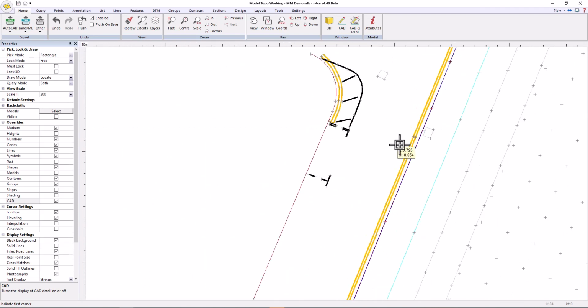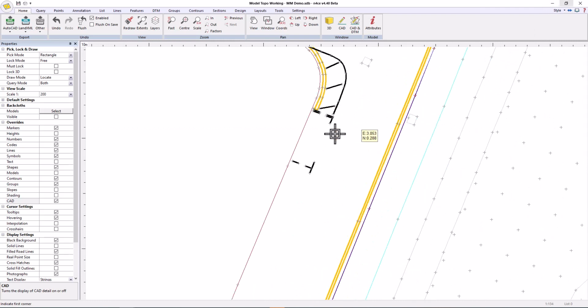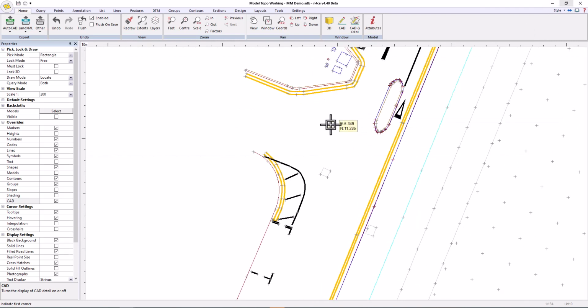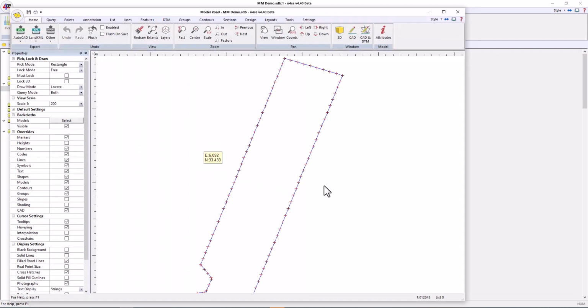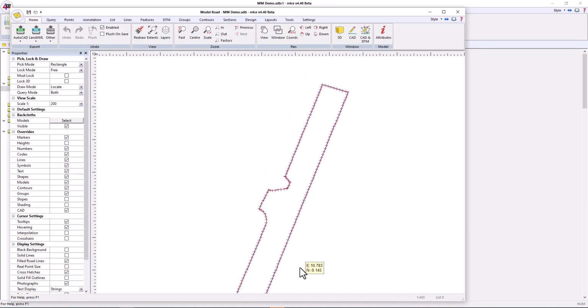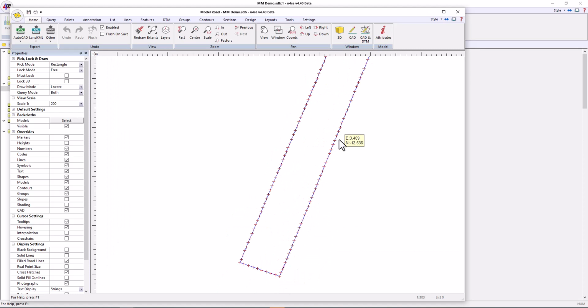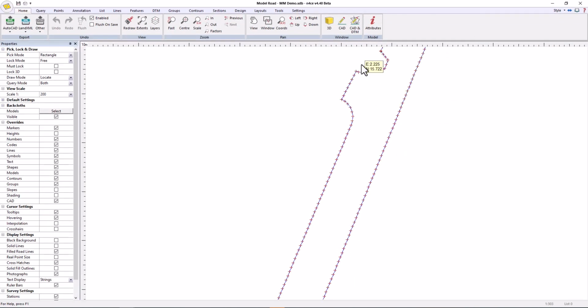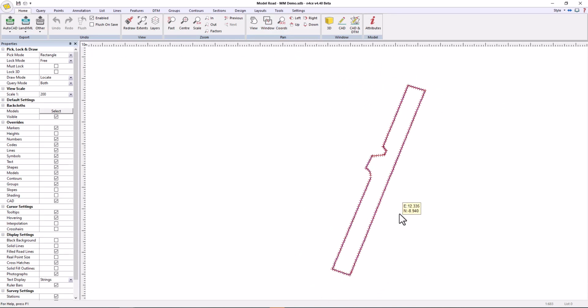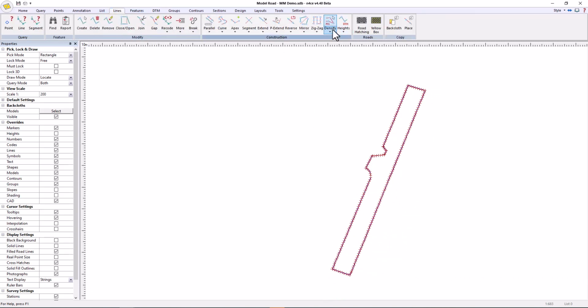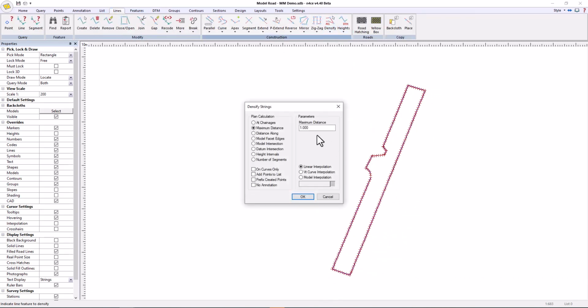The road I'm going to do a slightly different way. So I want to create a hyper accurate road model just to show that we can do that. So if I close down this view, I'm going to go into a model here I've already got called road. Okay, so this is the edge strings that I've digitized. Okay, and then densified. So I use the densify command to then make sure I've got lots of points at regular intervals, because I want to make sure I pick up the surface accurately enough, because this is going to be my edge. So I digitized it and I went to lines, densify all, and then gave it the distance. Okay, and interpolated onto the point cloud.